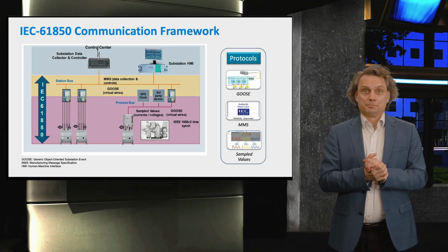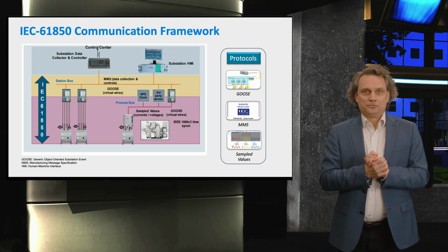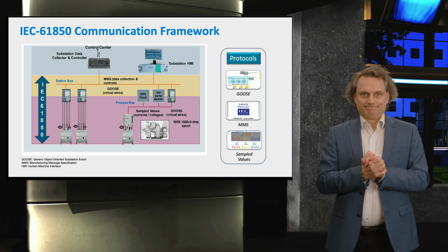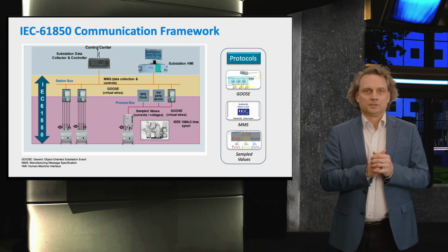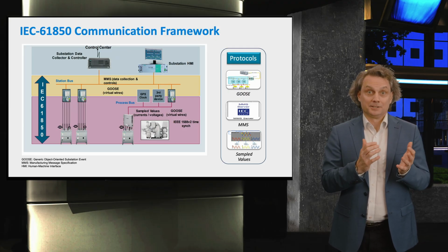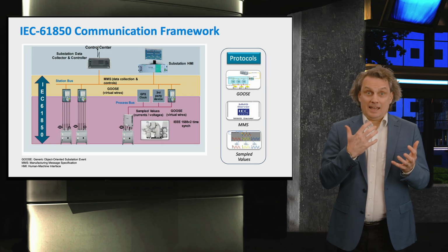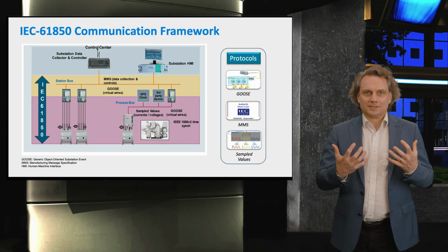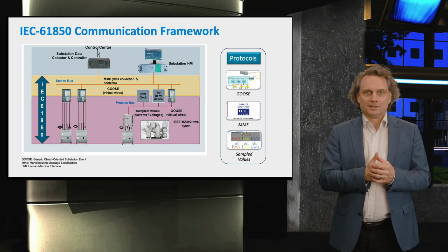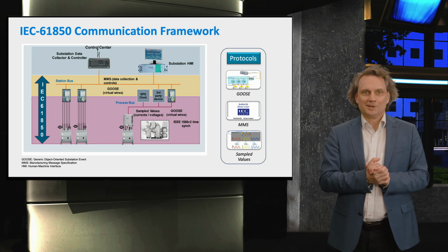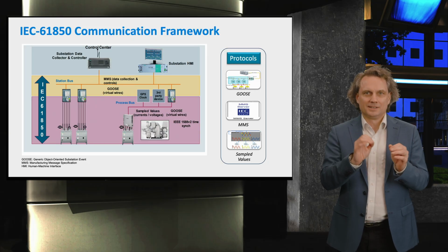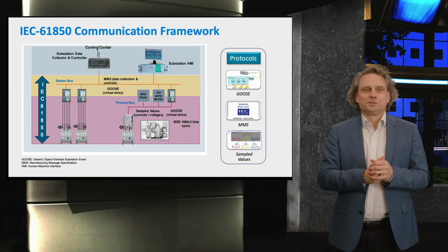MMS is a third protocol, Manufacturing Message Specification. It is used for configuring intelligent electronic devices, the IEDs. MMS is semantically rich. It is XML-based and can contain complex data. GOOSE, however, is very simple, very fast. It is sent, and speed is all that counts.